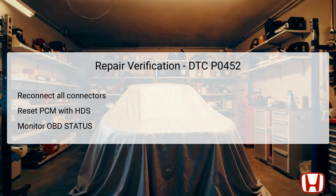After resetting, initiate the PCM idle learn procedure to help the system recalibrate itself based on any repairs that were performed. Finally, start the engine and allow it to idle while continuously monitoring the OBD status for DTC P0452 in the HDS menu. Checking here provides immediate feedback on whether the issues have been resolved or if the faults persist. If the HDS indicates passed, the troubleshooting is complete. If failed, further checks may be necessary.